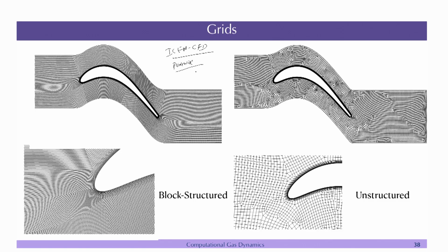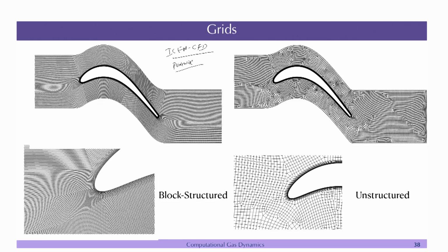So, what these tools do is basically they will give you very nice orthogonal grid, they will give you flexibility to define different blocks and construct grid. So, here for example, this is a blade in a cascade, that means you have a blade on top also somewhere here and a blade at bottom also, right. So, we have taken the distance between these two blades and put a top boundary, so that you can apply the periodic boundary condition here. So, you can apply periodic here, and similarly you can apply periodic here at the bottom.